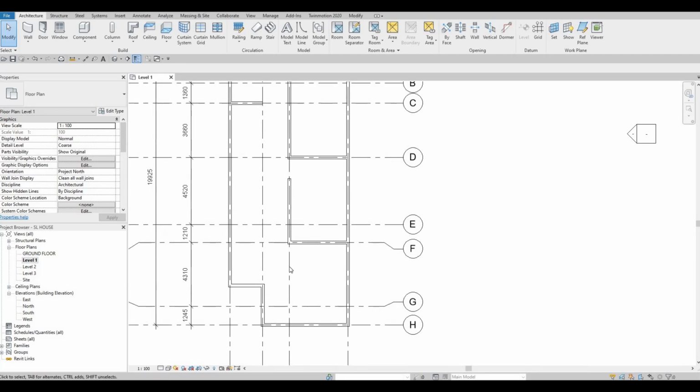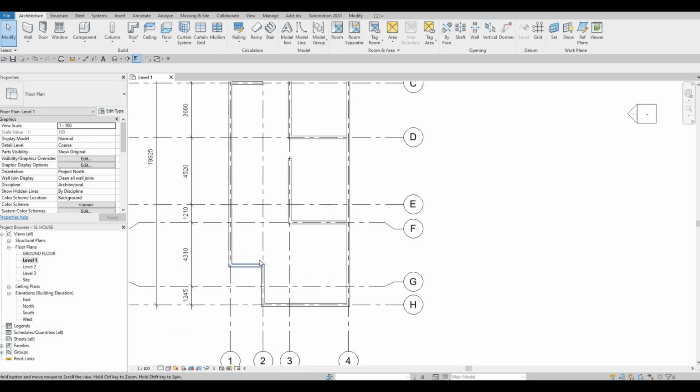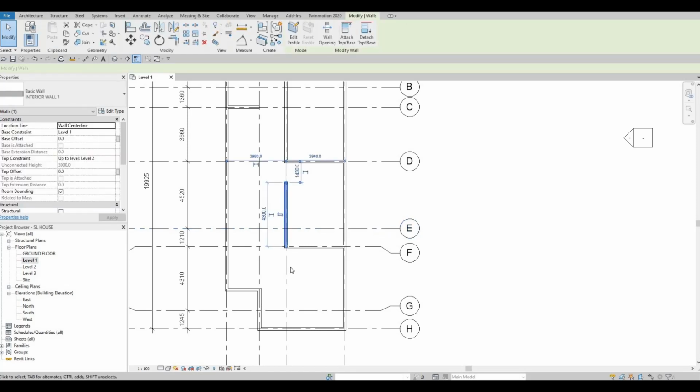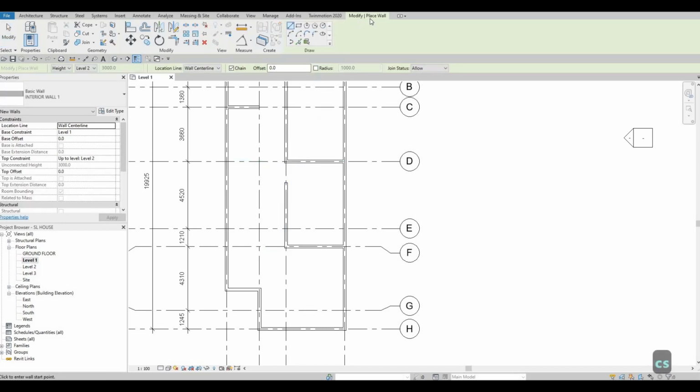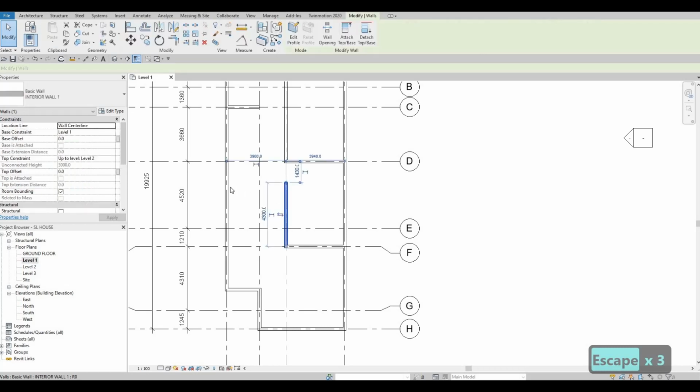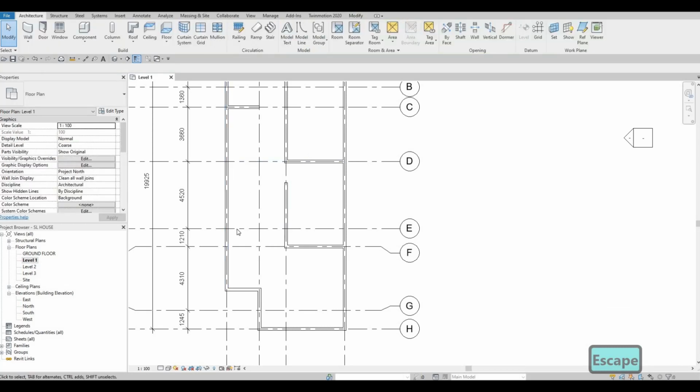And then after that, we need to add interior walls right about here. So here, select that, CS. So CS is create similar, that's under modify, and this is the icon for that, create similar. It's already grayed out because we already selected that. So now in terms of CS, whatever you choose, for example, if you want interior walls, furniture, or wherever, you will be able to add the same one instantly.